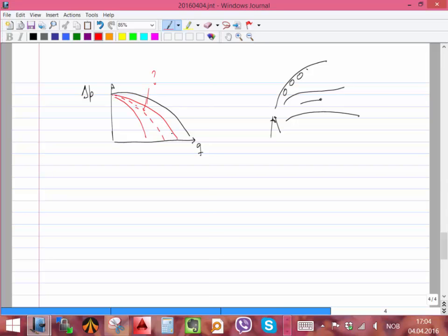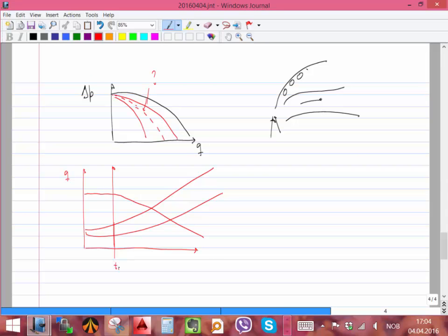And our main problem, as petroleum engineers, is that we have a lot of change in the life of the field. Our rate is going to go down, our GOR is going to go up, our water cut is also maybe going to go up. There are many changes. So maybe we know how our machine operates at this time one, but at another time, we don't know. It has different viscosity, different density, different GVF. So that's where the problem comes from.